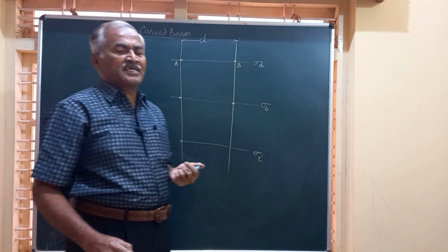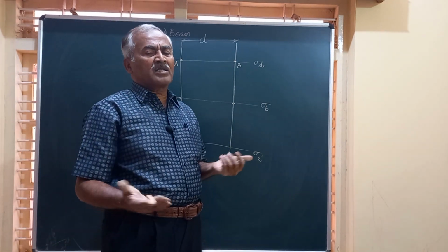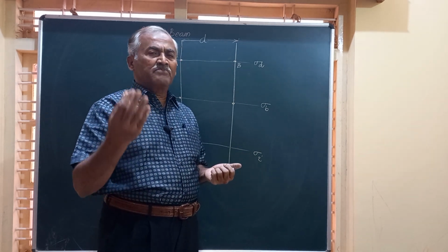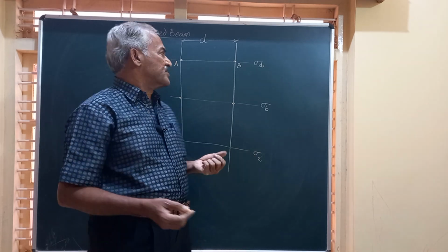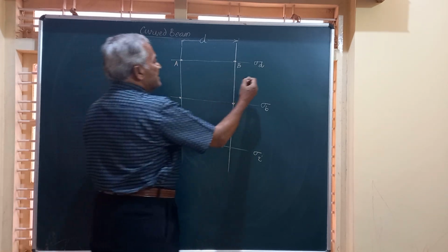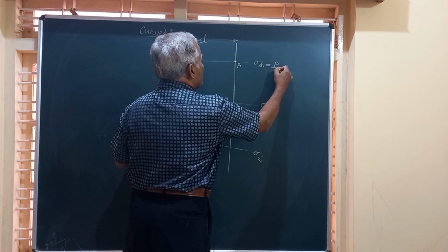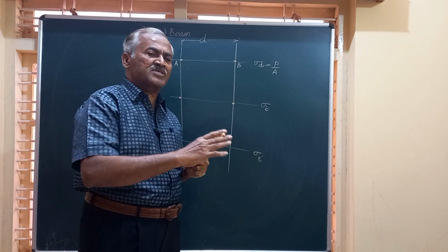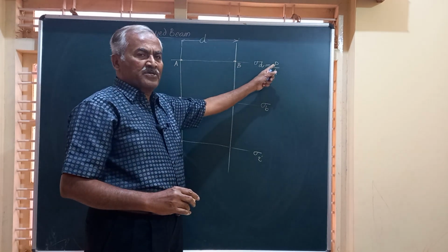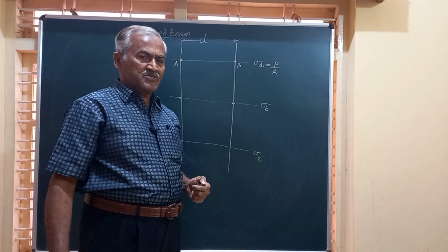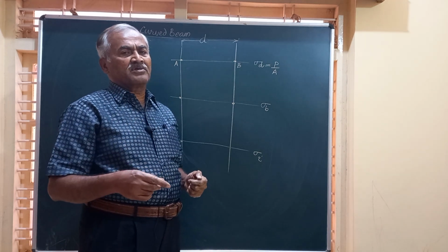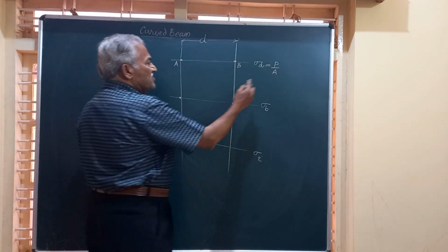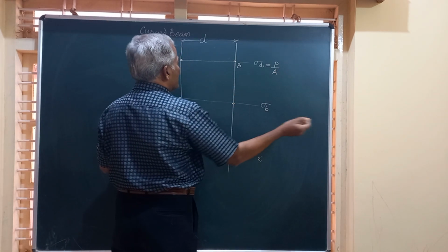So please follow clearly. It is a very simple step. Already you have made the calculation for all the stresses, direct stress, bending stress, and then the shear stress. Friends, sigma direct is given by the formula P by A. So generally for all the problems in this chapter, load should be given. Area of cross section will also be known based on the cross section. It could be trapezoidal, circular, etc. So friends, we know the load, we know the area, we have calculated.